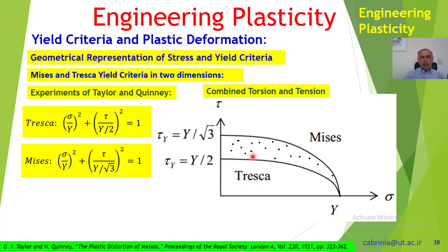As we have said here, this was for copper and similar materials. But if you have, for instance, cast iron, that would be much different. Maybe you get it here, maybe you get it there. So the behavior of the material and the composition of the material very much determines the yield criteria that we must use, but generally this is the case.